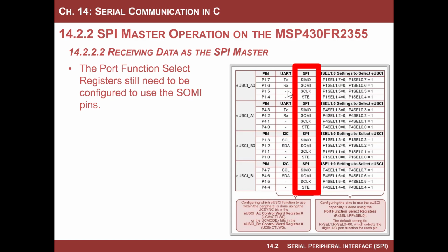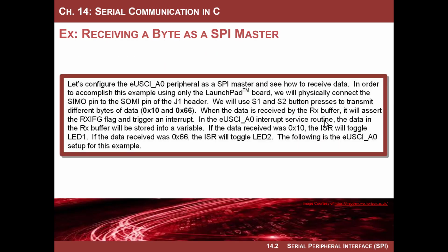Okay, we are using the slave out master in line, which we've set up before, but just remember that when we do that, it's a dedicated signal in the SPI peripheral, and we just have to tell the port function select registers that instead of using the ports, use this slave out master in.